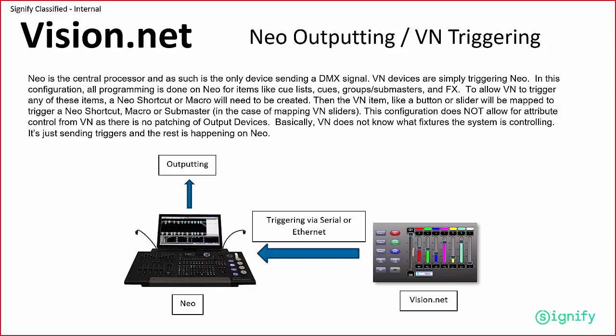Purely on an economy of scale standpoint, now this isn't about what type of control you need, but just on pure economy of scale, once you get above 4 universes, it's actually cheaper to no longer go with that same architecture of having Visionet to DMX cards, because once you get beyond 4 universes, you need an additional 8-port node to continue to have network ports or DMX ports available on the network to add additional cards.